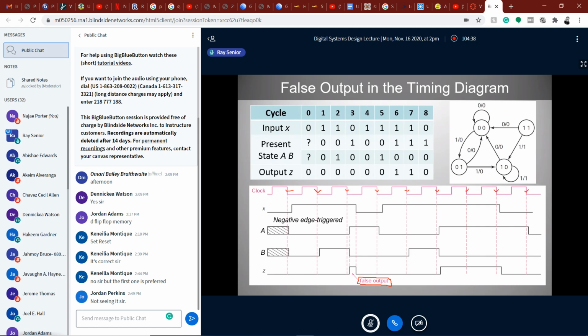Eventually, if you get back the correct value, it will come back down, or go up in the case where it is a false 0, or in this case we get a false 1. So it will level out to the correct value. But just after the clock edge and just before the signal changes, you will get a false value for Mealy circuits. This is one of the drawbacks with a Mealy circuit. But it levels out for the clock cycle, and we are certain that just before the clock edge, the correct value for the output is available.